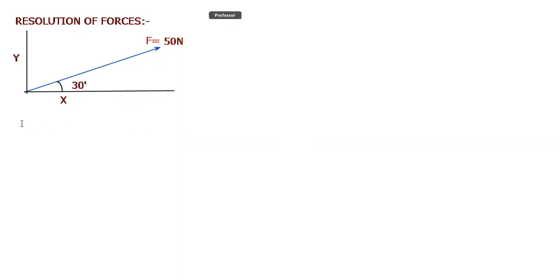Then how we can resolve this force as Fx equal to, that is the component of force 50 Newton along the x direction is equal to 50 into cos of theta, and theta is your 30 degree.